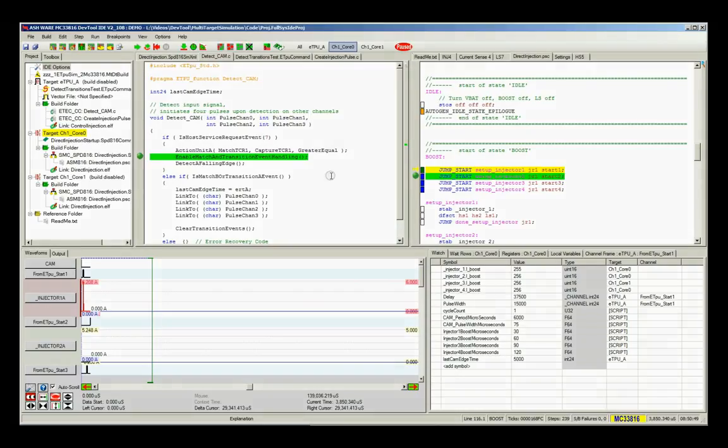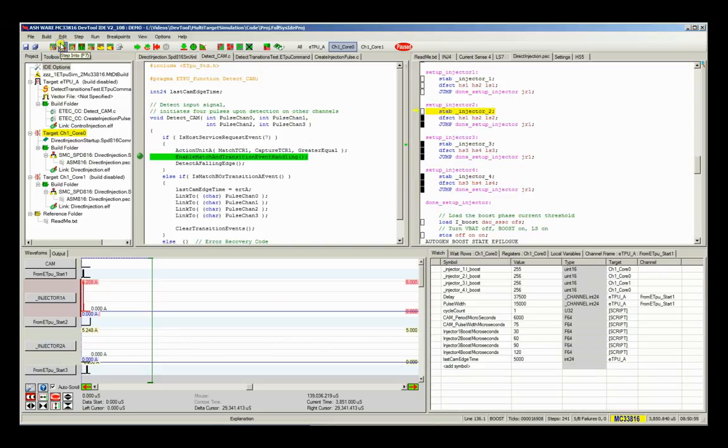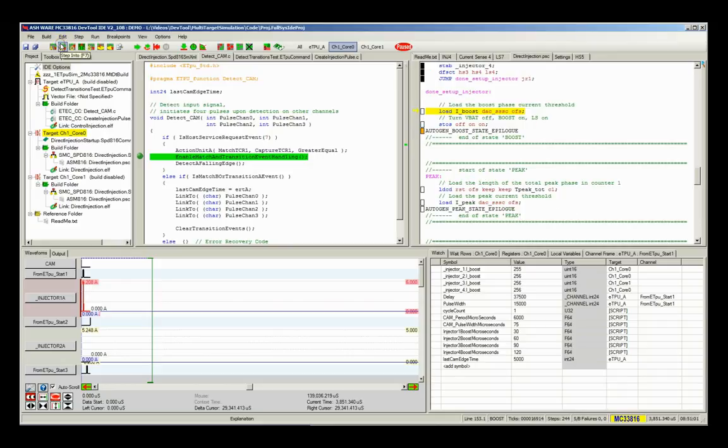Core 0 has been idle, so it takes until 3.8 milliseconds before it steps a line of source code. Let's step several more times. Note that on each step the yellow lines change, indicating that Core 0 is stepping down through its source code, one source code line at a time. Some steps take longer than others due to the core waiting idly at a wait instruction.